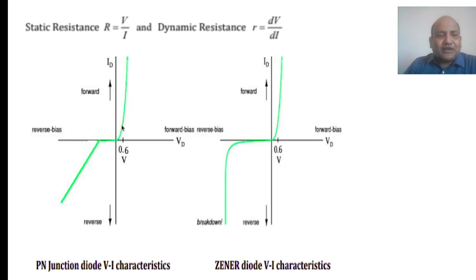Another point you can calculate from this graph is your cut-in voltage. Take the exponential region. From there draw a straight line to the voltage axis, and where it cuts, that is your cut-in voltage or on voltage.